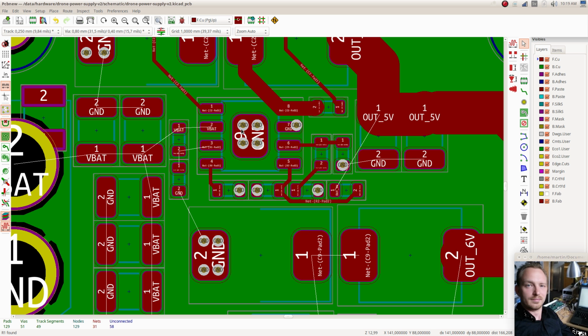So when I also generate these custom footprints, I have gone for the rounded edges, because I've seen in the IPC somewhere that the recommendation is to actually use rounded edges for the packages, because it seems to produce better results. About the board density, so KiCad doesn't normally provide different board densities, but it's very useful for placement.